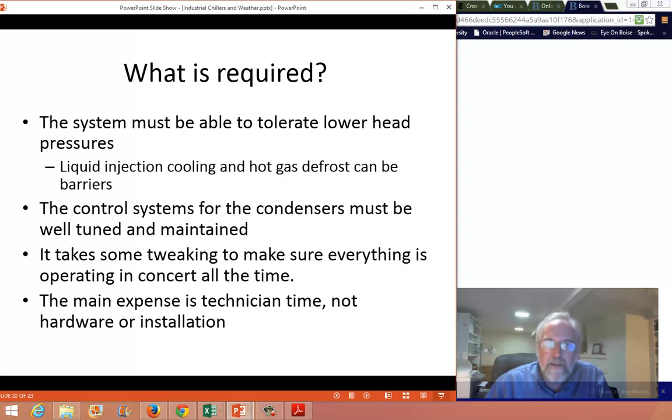Sounds easy. It turns out that these things are incredibly finicky. What most operators do is they say, well, the lower the pressure is, the more likely something might go wrong. I just keep it high because, heck, I'm not paying the electric bill. And again, there are certain quirks in the system that may require it to be higher. As efficiency engineers, we're not trained refrigeration design engineers, but we can certainly have this discussion. Say, okay, what is it that's limiting you at your minimum pressure? This sort of analysis can tell you how much money is at stake by running at a minimum pressure that's too high.